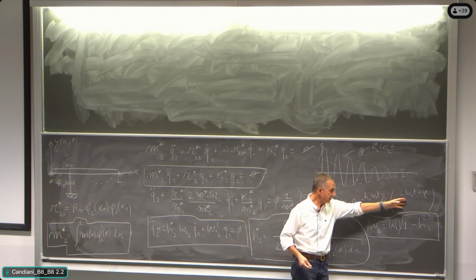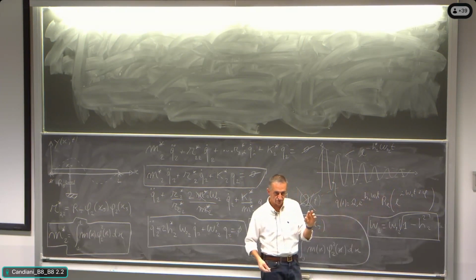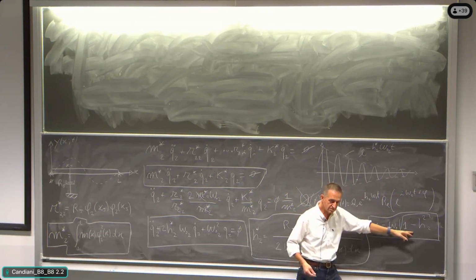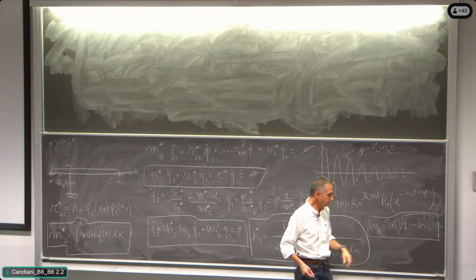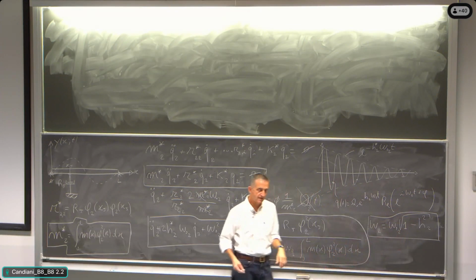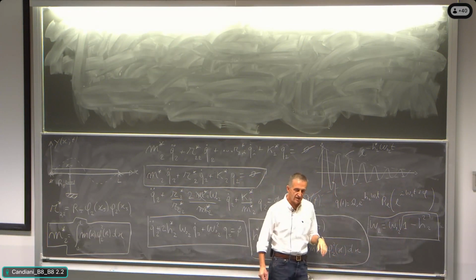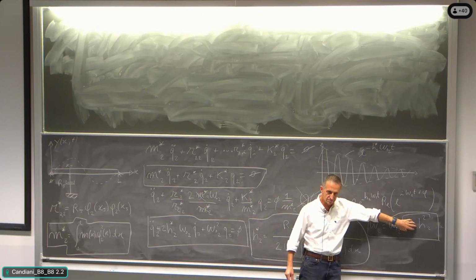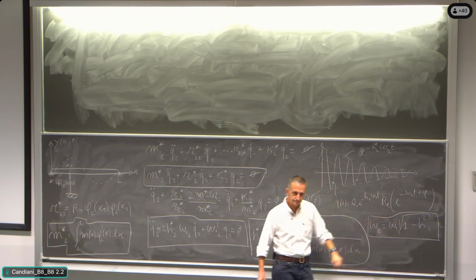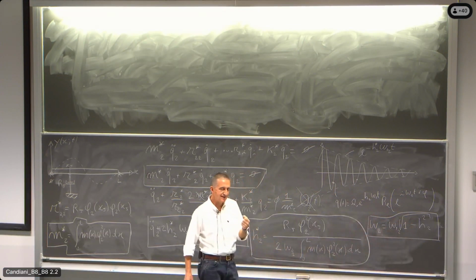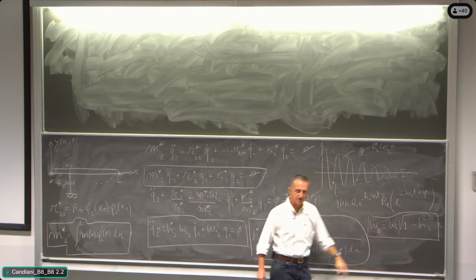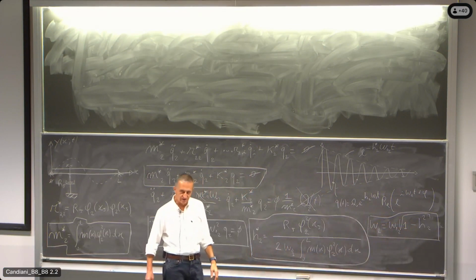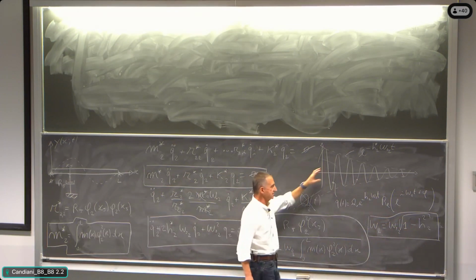And then the oscillation will be at a frequency that is not exactly omega 0,2, because it is a little bit different. It is different because it is weighted by the square root of 1 minus the square of the non-dimensional damping. We should also be very aware that this correction is small. What is the amount of this correction, in which percentage is the natural frequency of the system changing because of the contribution of a damper?